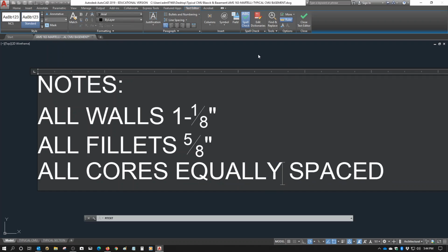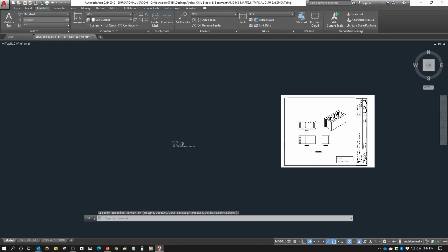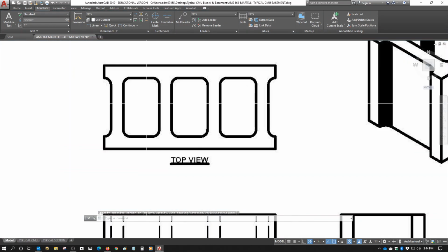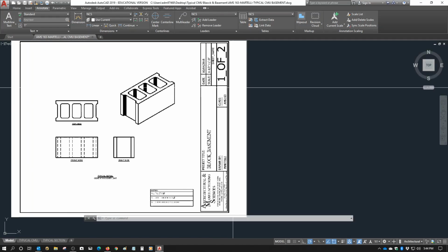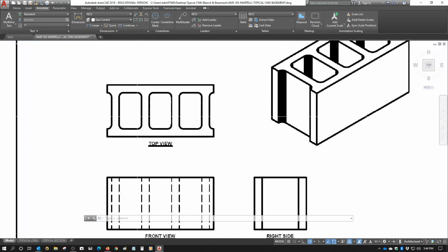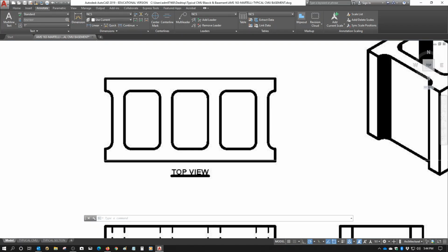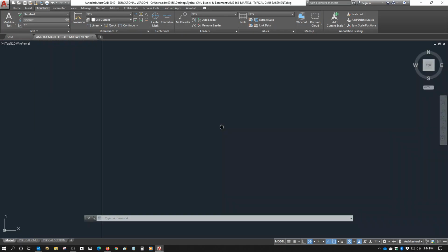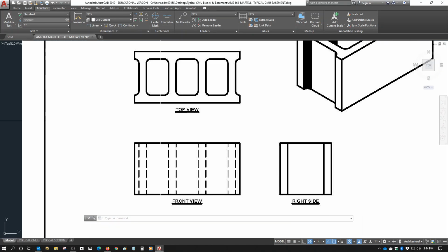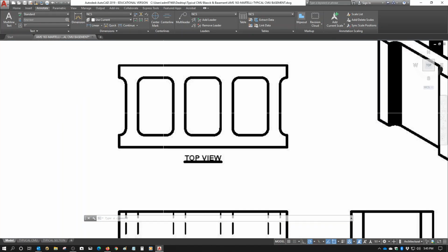Very good. So first things first, I put these little notes in here. Next, something about these concrete blocks. They call them an 8 by 8 by 16. In other words, it's going to be 8 inch by 8 inch tall by 16 wide. But they're not actually that tall. In fact, what they are is 3/8 of an inch less than that, because your grout seams, the grout that binds all these blocks together to assemble a wall, is going to be 3/8 thick. That's how thick mortar should be.